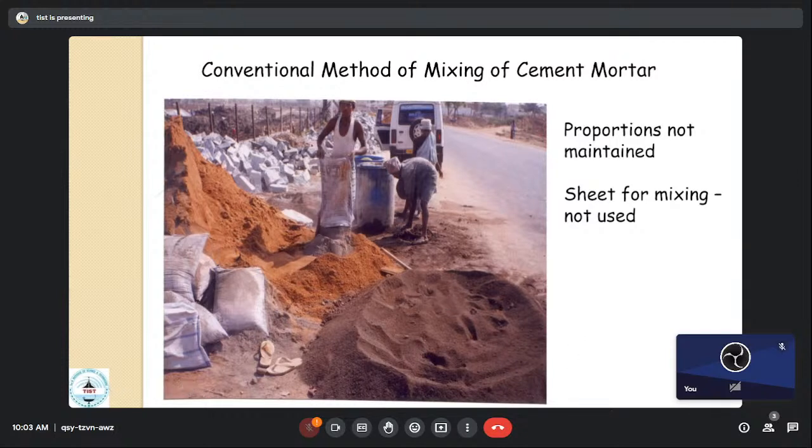So what is going to happen when you plaster it? That is going to weaken it, or when you do the masonry, that is going to affect it. Those pebbles have to be removed. For everything there is something known as a proportion, right? Yes or no? So what is the proportion we normally follow? 1:5 or 1:4 for brick masonry, right? 1:4. Like that, there is some proportion. Have they followed any proportion over there?